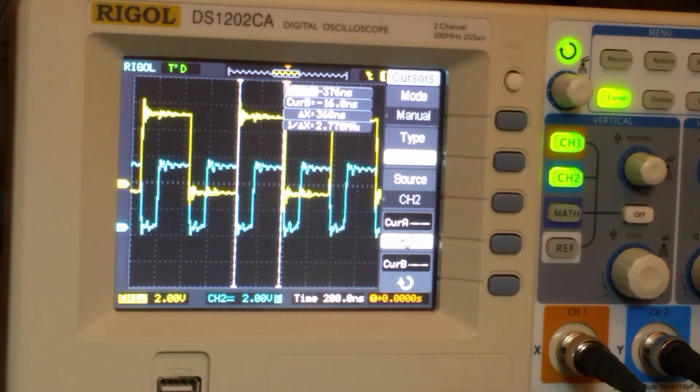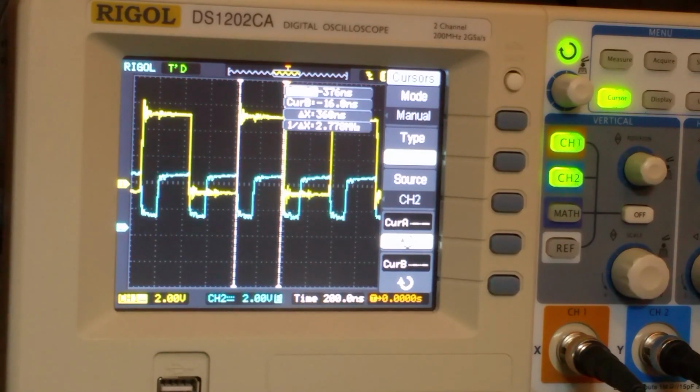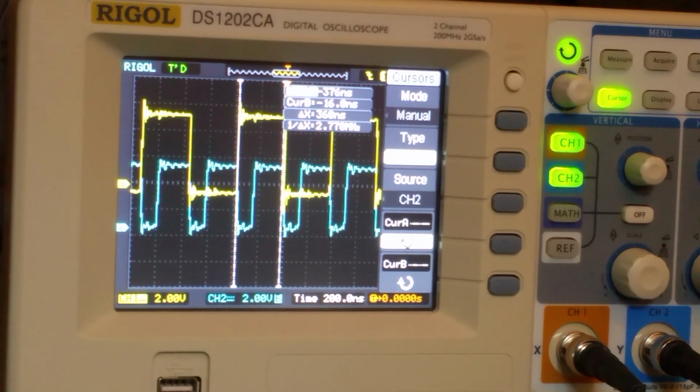and this is actually what you can see here, this is the ready signal. So actually it shows that the first cycle is reading the opcode, which takes 2 cycles, one with ready, then actually reading it, and then there is another cycle where the CPU does nothing, and then it increases the memory address and goes to the next execution.